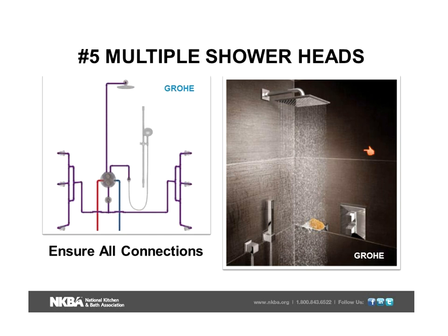Now, over to the right is not what we see to the left, so I don't want to throw you off. But in this particular case, same manufacturer. So they have a suggested location for the body sprays and a suggested hookup. You see how the water is kind of going in at different places, so we don't have all of the water pressure at one particular body spray. We want to have a high volume valve so it'll handle all of the water coming in and get it distributed out evenly.